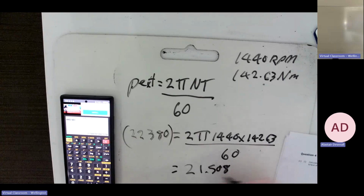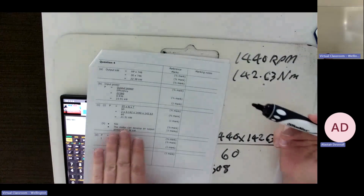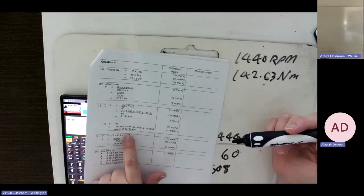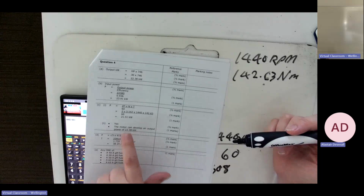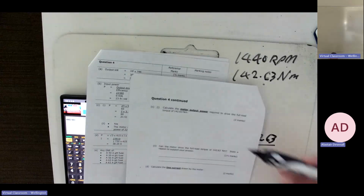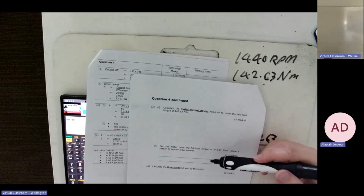Move it up 3 decimal places, and it's 21.5 kilowatts. As we have worked out, 21.5 kilowatts is required, and the motor can output 22.38 kilowatts. Yes, it may make the motor go, as per our questions on C1 and C2.